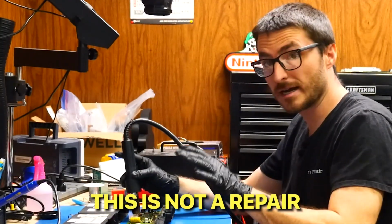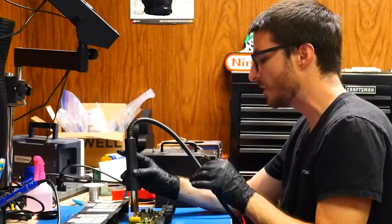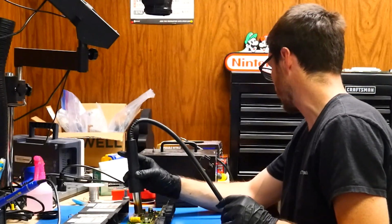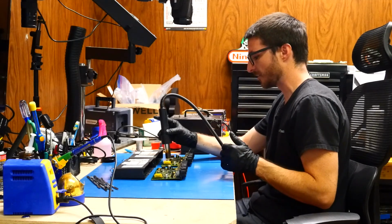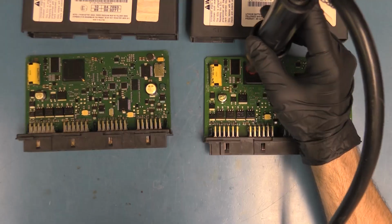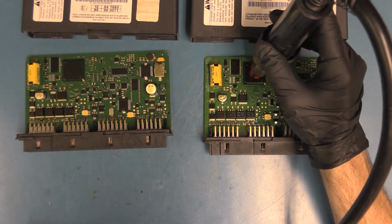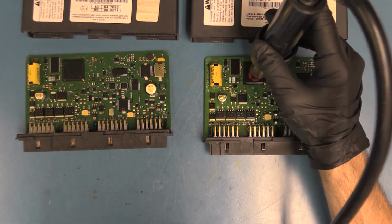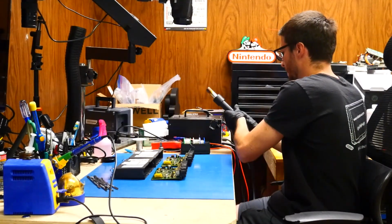Now again, this is not a repair. This is just for us to diagnose and confirm the exact fault with this CPC4. Now this is also something you can do if your truck is currently broken down on the side of the road, or it's in a bad spot and you need to just temporarily move it, is heating up this processor. This will allow the CPC4 to temporarily work, so you can at least move the truck to a better location, but then you will need to have it actually fixed or replaced.